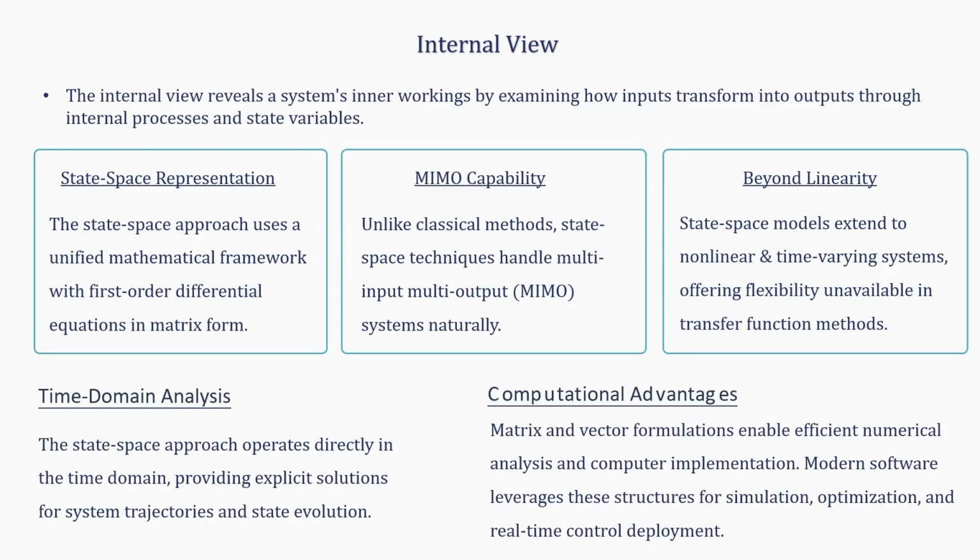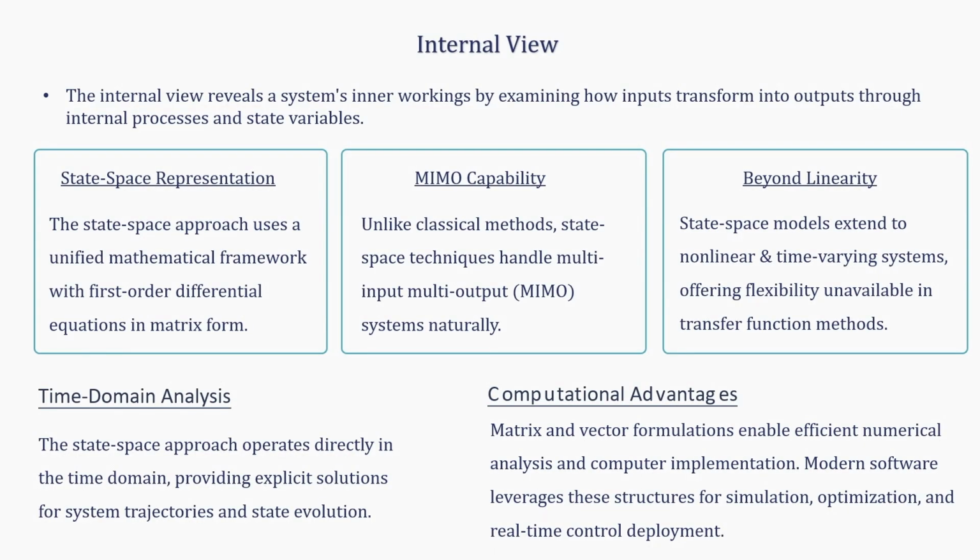Now, the state space approach operates directly in the time domain, like the transfer function used to operate directly in the frequency domain, because s was complex frequency, if you remember. State space representation operates in the time domain. So, in some sense it is a time domain approach as well. And since we will be dealing with matrices and vectors, this approach is numerically implementable. By numerically implementable, I mean that software packages can easily handle this type of modeling because there are matrices and vectors involved here. So, from a computational perspective also this approach is better.